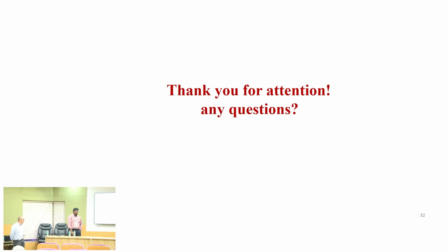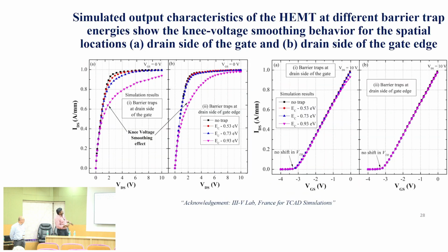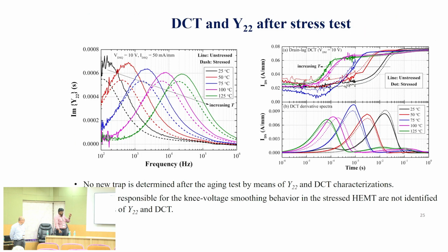But in this case, high temperature reverse bias, the transistors are stored at higher temperature as well as under reverse bias during the operation. So both electrical and temperature stress. The maximum temperature you keep it at is 175, right? Yes, 175. The devices are stored at 175 degrees centigrade for 1000 hours. After that, the measurements are carried out at normal condition.